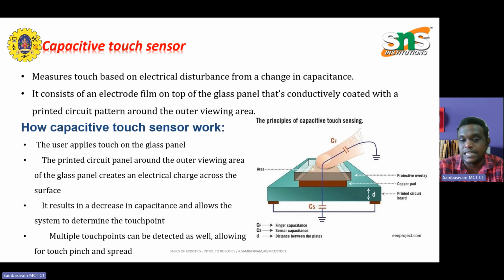As shown in the figure, if the area of the sensor electrode is bigger and the thickness of the covering material is less, the touch capacitance is also bigger. As a result, the capacitive difference between the touched pad and the untouched sensor pad is also big. This means that the size of the sensor electrode and the covering material will influence the sensitivity of the sensors. The measuring of capacitance is used in many applications by determining distance, pressure, acceleration, etc. Measurement methods include frequency modulation, time delay measurement, duty cycle, etc.